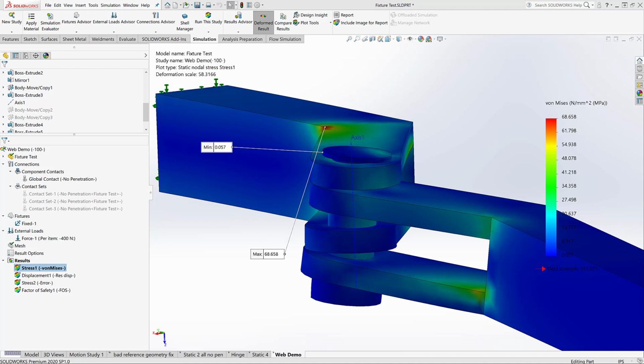What you can do instead of giving it a gap clearance is you can just emulate the parts being held together. You can essentially say that it's bonded and specify how much force is being applied to that area as well, and that should also give you a good way to model it without having to necessarily put in a pin. So I'll show that next too.